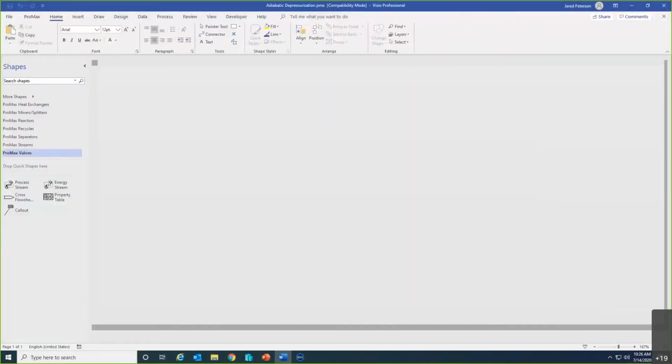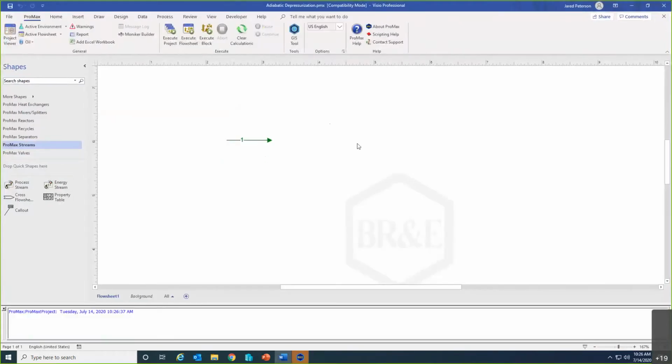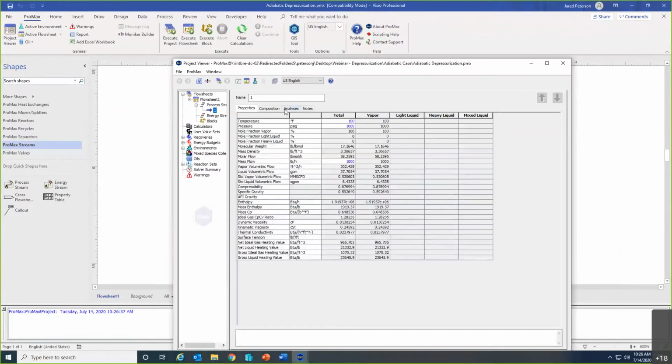As I've mentioned, we do need to set up the conditions for our system with the conditions that would be in our system right before depressurization, right before relief specifically. In this case, I've already created a stream for us, and I'm pretending these are the conditions right before relief. We'll be looking, once we get to the fire case, how to create these sort of conditions.